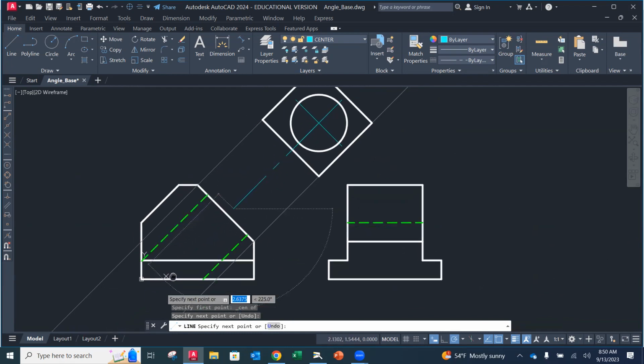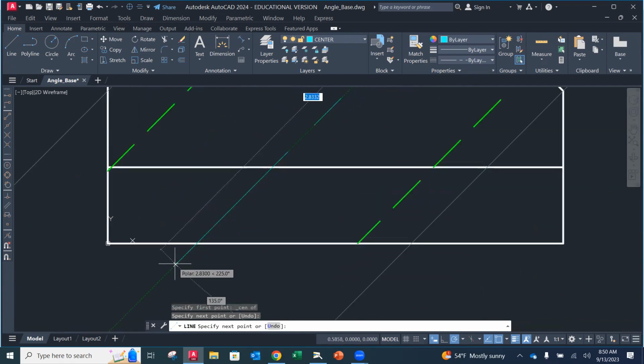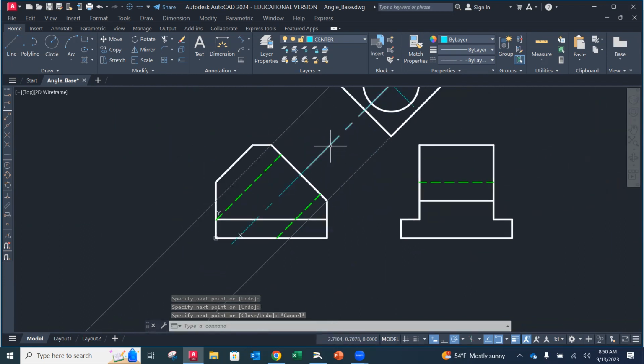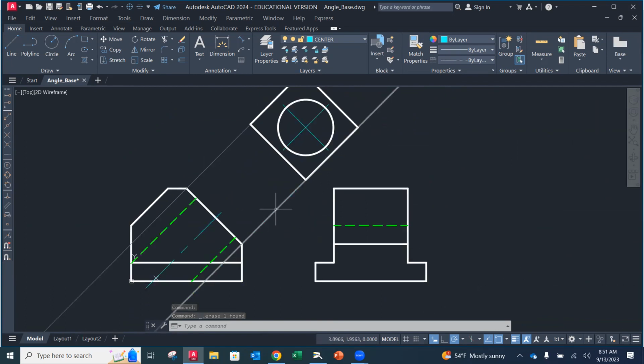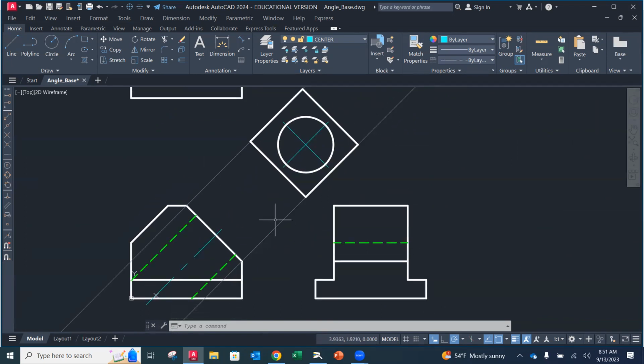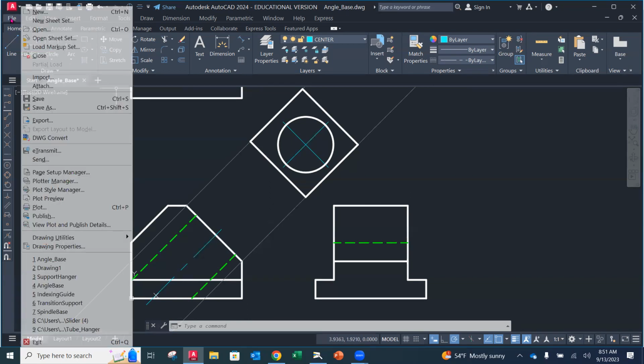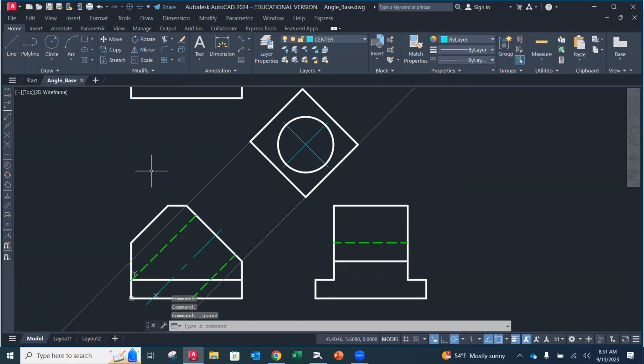And then I'm going to go down and zoom back in down here, and I'm going to go beyond a little bit. Okay. And then that way I have that separate line again. I can grab this one and I can simply delete it. We don't want to connect between views center lines. It's illegal. Okay. Quick save. We are looking good now, don't you think?